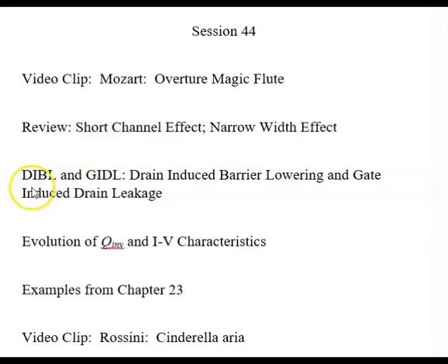And then we'll move on to something called DIBL and GIDL. DIBL is drain-induced barrier lowering, and GIDL is gate-induced drain leakage. And we'll see that these, like the short L and the narrow width effect, are somewhat complementary, not quite as complementary, but they both involve the drain. One is drain barrier lowering and the other is drain leakage.